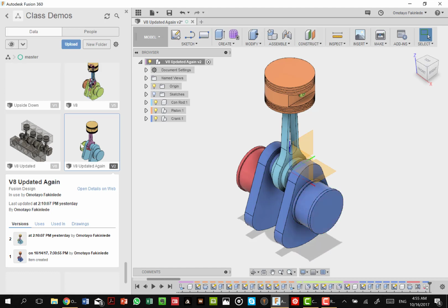Now we have the rotating portion of the crank, and then at that edge we make these two ends. We use the method we have already described to create the position for the pins to hold the two portions of the connecting rod together, making the holes on the connecting rod as already been described. Now we have a cutting plane, cutting this into two,